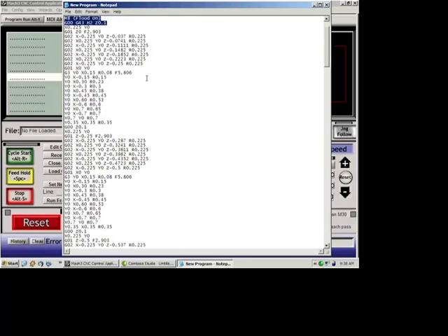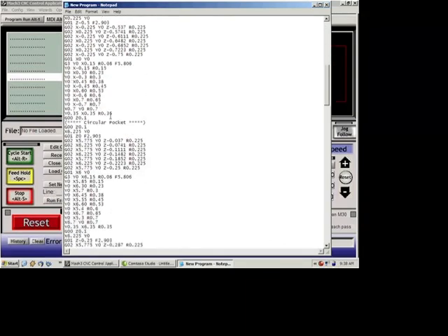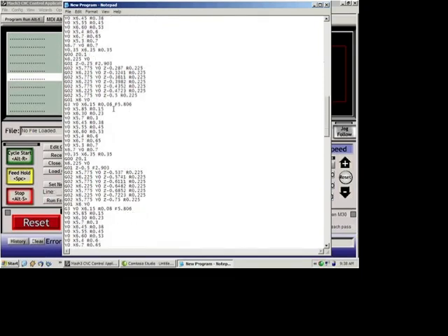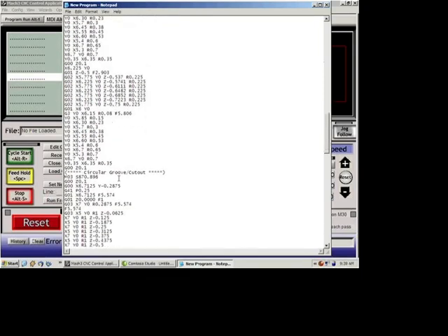And if we scroll down, we'll see that we have our next circular pocket, but we don't have any tool data. This is because we didn't select any new tool data. Whereas if we go to the next section on our groove, where we were cleaning out the pass, we did change our spindle RPM, which is why we now have that command.